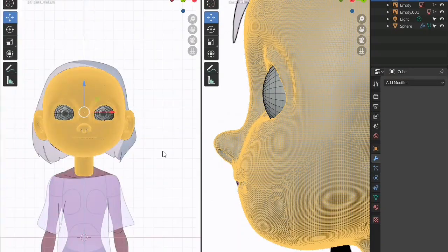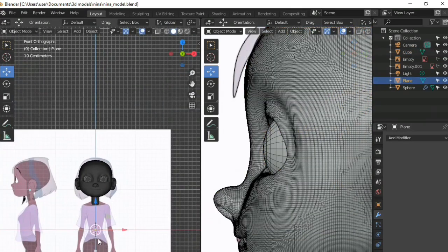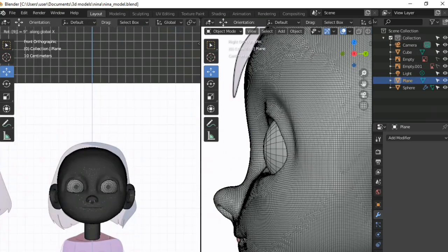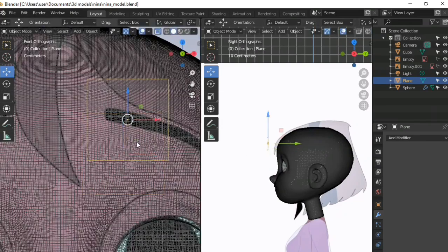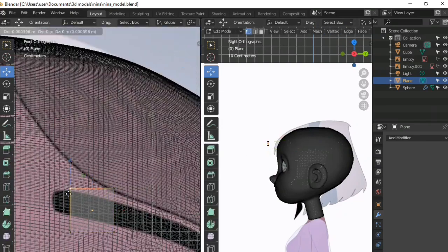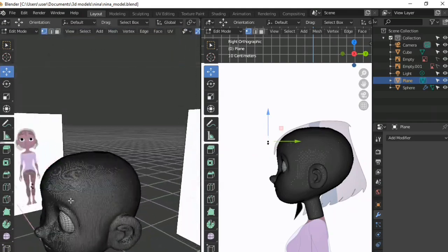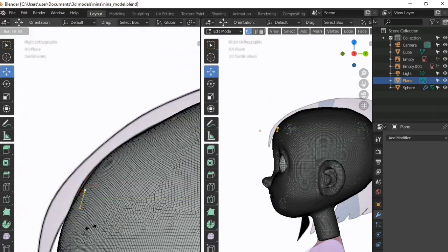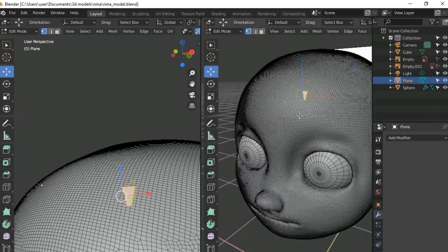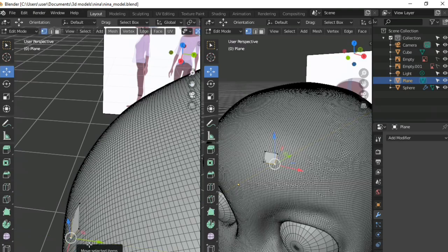So what we'll do now, we'll say Shift A on our keyboard to bring in a mesh. So let's select plane. Let's rotate that plane, X 90. So we use this plane for the eyebrow. We scale the plane to this head area. Take it up to this head area to where we have the eyebrow. Then let's adjust it like this to this point. So what we'll do next, we're going to push this backward a little bit and rotate. Alright, so I want it to be on top of that head area. Yes, directly like this. So just try and adjust it this way.